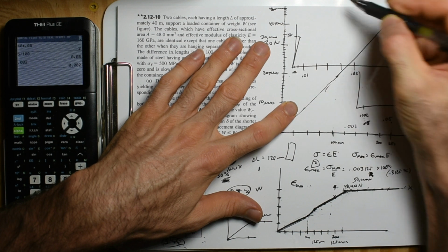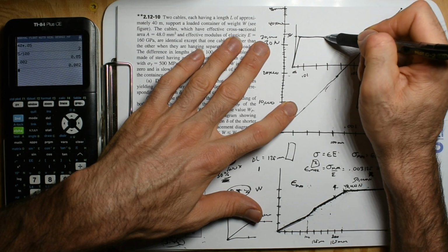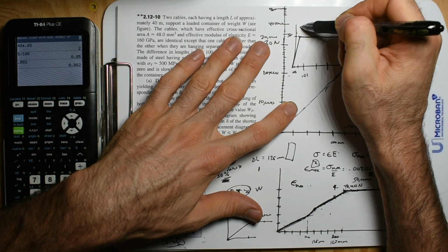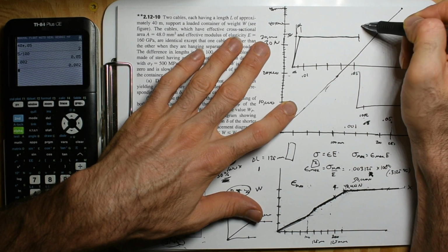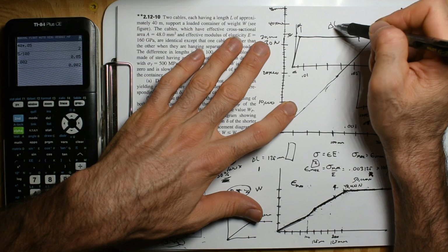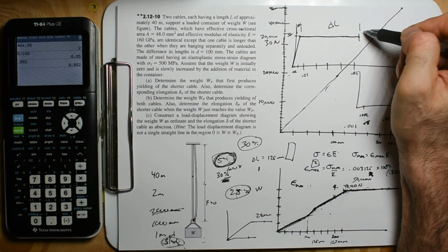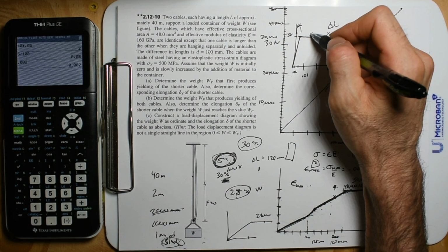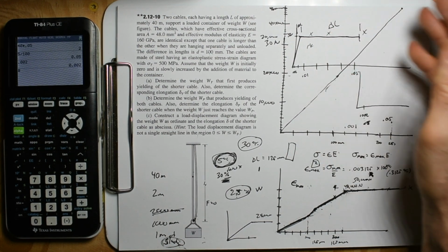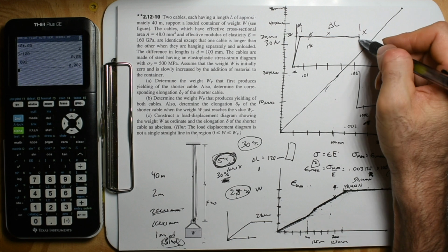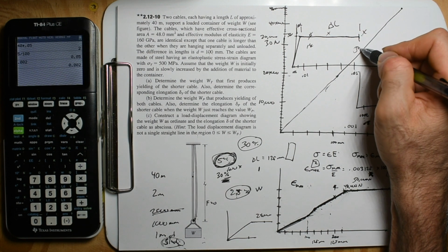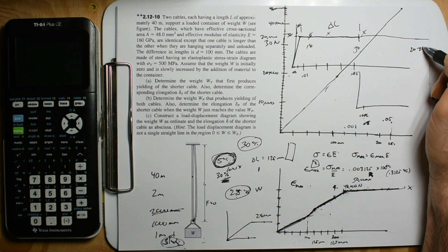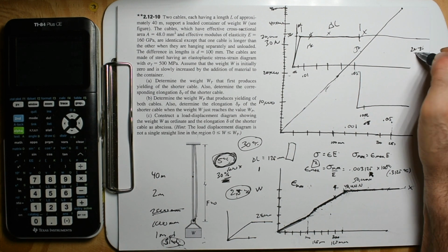Here would be your line. See how steep as hell that is? And then here's your elastoplastic. This is how far it could stretch. Comparatively, this change in length is potatoes compared to this elastic change in length before crap actually does break. But like I said, you could have something funky go on, and this could break at 1% for all we know. But it can break up to 5%, and with steel, sky's the limit. It could go up to 20 to 30%. It can happen.